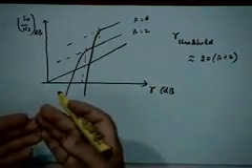If you go for larger values of beta, you get better output SNR provided the input SNR stays above the threshold value. But at the same time, you are buying the probability that unless you are significantly above the threshold value, you can come into the threshold region and suddenly you get a very large noise at the output.